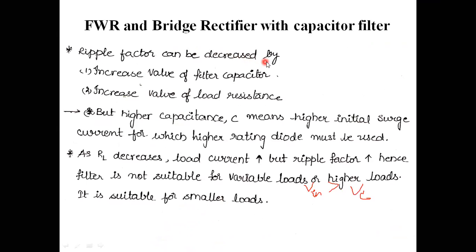And the ripple factor can be decreased by increasing the value of the filter capacitor. By increasing the filter capacitor value, I can decrease this ripple factor.